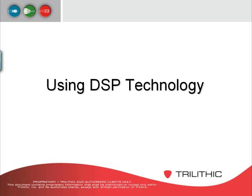Trilithic uses digital signal processing. With swept-tuned analyzers, there's a sweep pulse that runs through the frequency spectrum, and if there's some ingress that comes in where the sweep pulse is not presently at, then it will miss it. So the likelihood of you catching real fast transients gets a little slim.